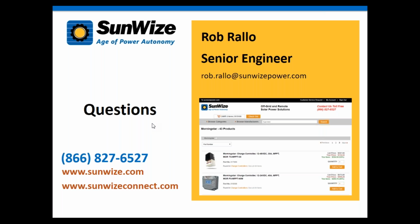Again, we have a tech note we're putting up on our website right now to address this, because as I was putting this webinar together, I realized that was not addressed very well. So I've created a tech note just for that. And again, what will end up happening is it'll bypass that section, and by doing that, it'll avoid the hot spot. And again, if you do have a max power point tracker, it will allow the rest of that solar module or string to function. And again, it literally just bypasses it. It just takes that section out.